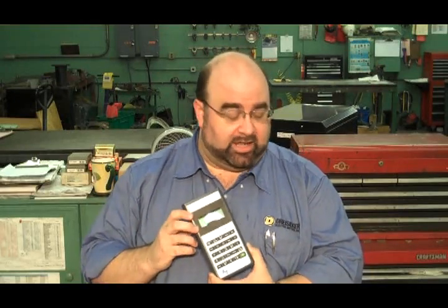Baker, PDMA, and Arriva also have similar test equipment for taking a look at the electrical system while something is live. It's called motor current signature analysis or electrical signature analysis. The difference between those is that my motor circuit analysis test equipment is going to tell me what's going on in my insulation system between conductors, in the air gap, in the rotor of the machine. It's going to tell me if I have turn shorts occurring or other insulation problems that I will not see with an insulation resistance test.